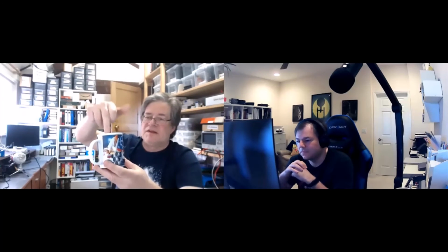About 2 years ago, I worked on a system with 3 dispensers in series. If you imagine, I want to fill this with something, and it moves along on a conveyor belt, stops, some things go in, goes to another position, some more things go in. And because the customer wants things to happen quickly, you have possibly 3 of these containers being dispensed at the same time. So you've got 3 sets of valves, 3 sets of pumps, 3 weighing scales, plus at the end there's a mixer, plus there's a guy pushing tubs on at the beginning. I'm watching a mimic screen with copies of the hardware happening on a screen in front of me, and I can't keep up because there's too much happening at once. You have to do things asynchronously.